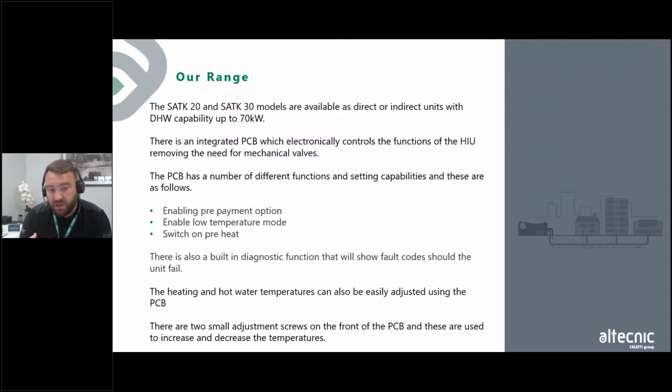We've also got a built-in diagnostics function, and this will show fault codes, which is a big benefit for us. So if people ring us up saying my HIU's not working, we can say, okay, what fault code is it showing? If there's not a fault code, it's generally not the HIU. It's something to do with the system itself. So we do have a built-in diagnostics function, which we have a list of fault codes for, which we can talk through how to repair over the phone or send an engineer out to look at.